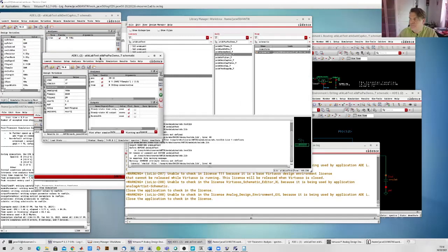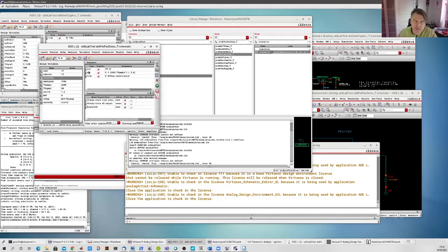Okay. All right. So there is a PSS, which is a periodic steady state. So you who are taking the RF course have probably bumped into this analysis type. What that analysis does is assume there is a steady state, a behavior which is cyclic, periodic, repetitive, which a sinusoid is, for example, or a square wave, or anything that repeats itself. A sinusoid typically has extremely low bandwidth, just existing in one single frequency, whereas a square wave has several tones associated with it: at f0, 3 times f0, 5 times f0, etc.